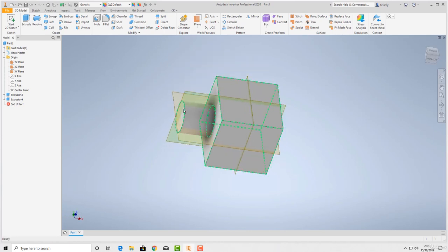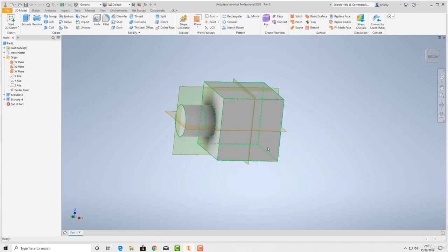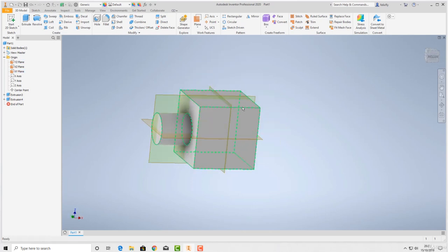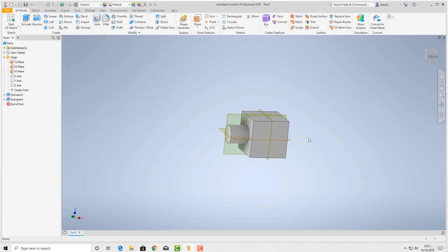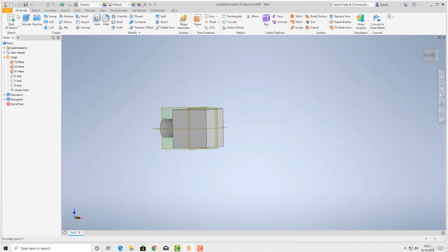And we have our 25mm diameter circular protrusion coming out there. Now I want this on the other side as well. I want another one exactly the same coming out of this face. We could go through the same thing, we could put a sketch on this face and extrude it, but this is a benefit of drawing symmetrically around our plane.